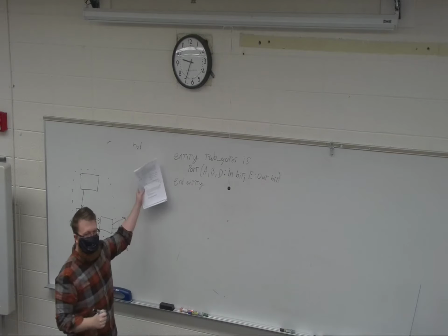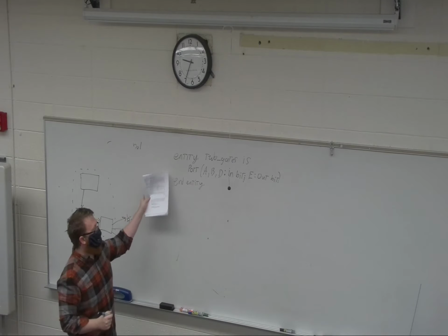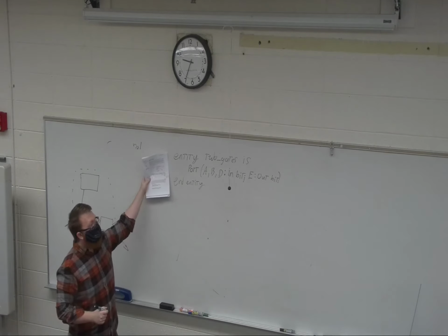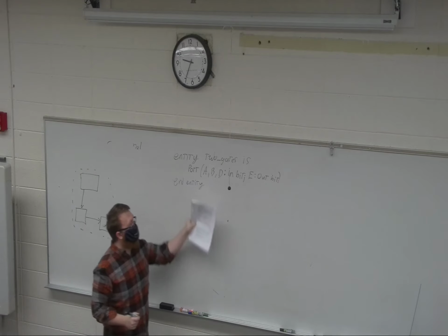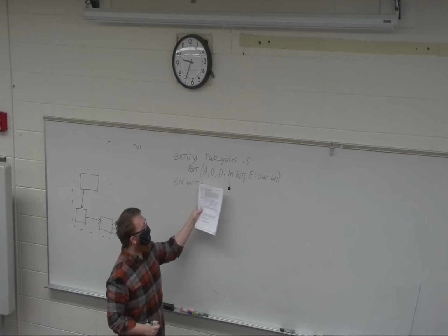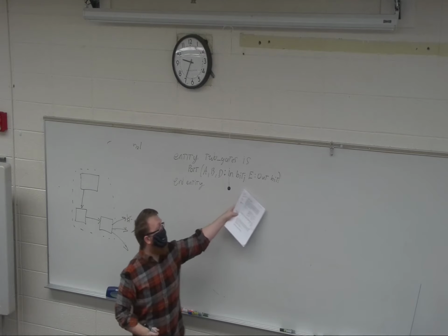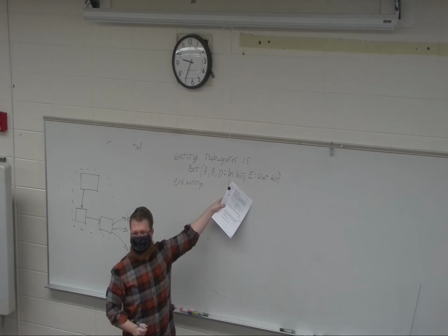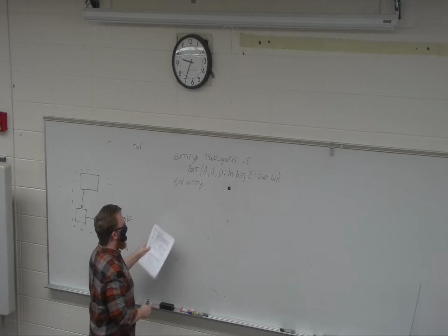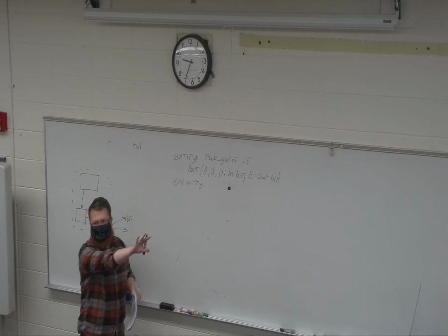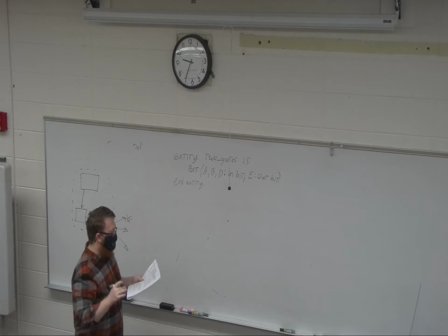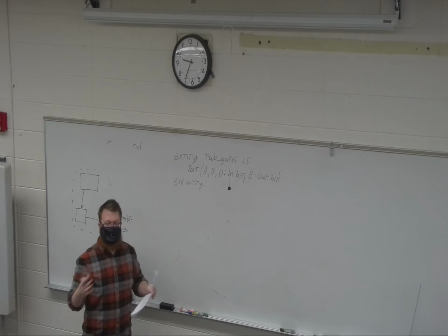So this is where we start to make a module. Now you'll notice this doesn't tell us anything about what it does, but it does tell us what ports are going to exist, and not only are they in or an out, but also what type they are. So these are going to be bits, right? And this is the same AND OR gate that we're going to build up that I drew on the board earlier. Then this needs an architecture.